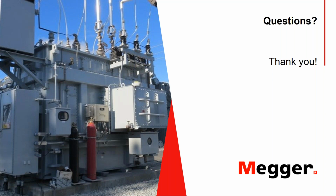And the other important aspect of demagnetization is that you have to vary the polarity and the magnitude of this demagnetization current. One technique involves changing the magnitude and polarity. You start off with a negative 10 amp current, then you change the polarity to positive 6 amps, so that all the magnetic domains in your transformer core become randomly aligned as they were when the transformer was de-energized.